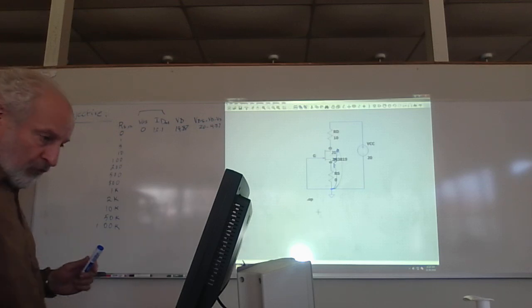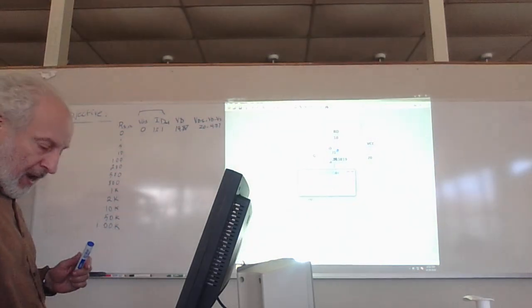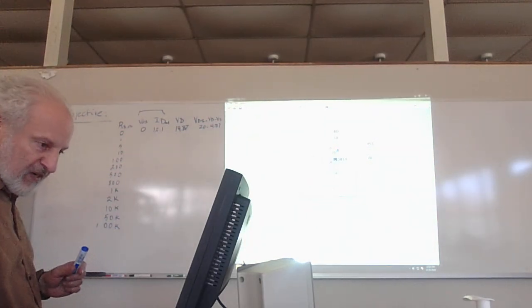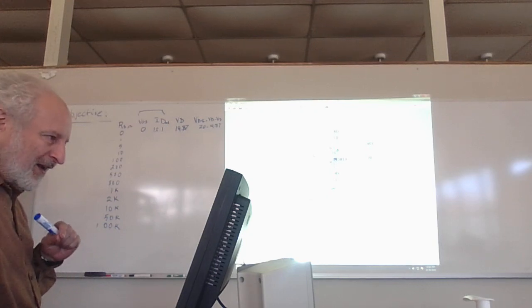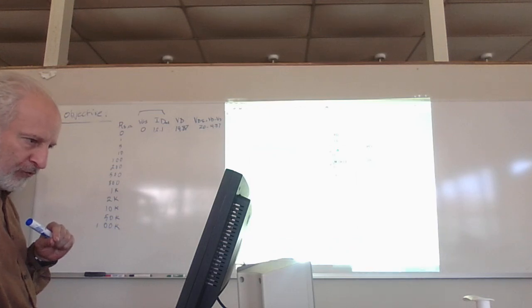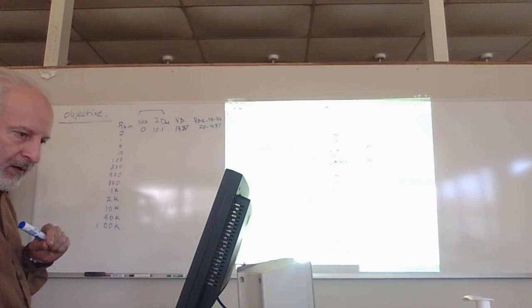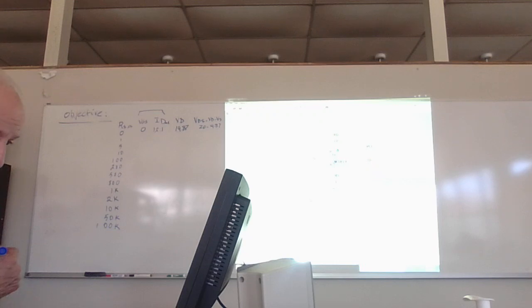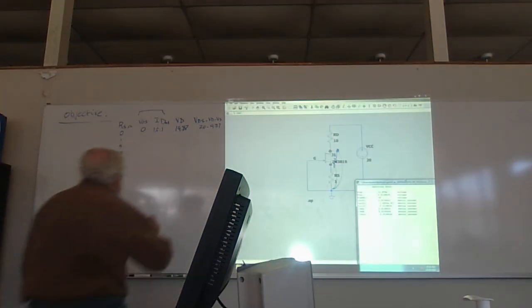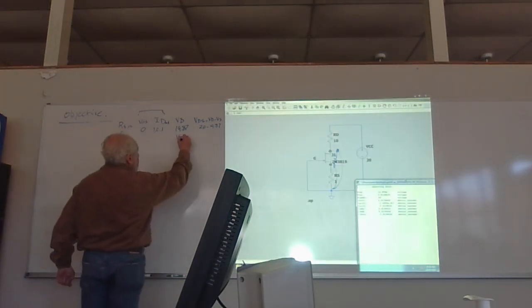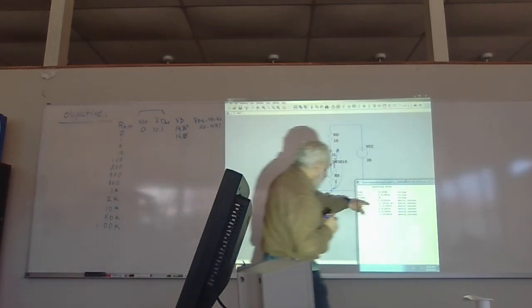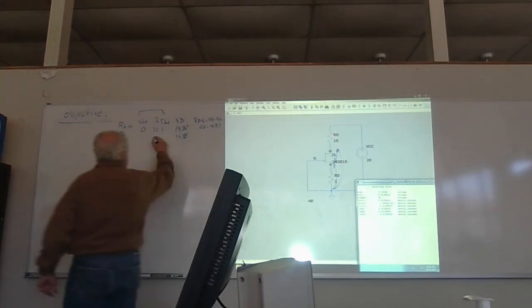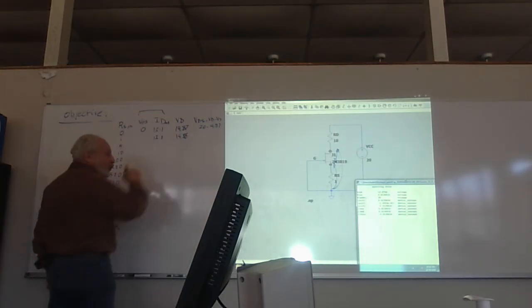Yep. So let's go ahead and run this with 1 ohm. Now, with 1 ohm, we should see a slight difference, but not that much in the current, because we're not resisting the current as much. Okay, good, so the other points showed up. We're still at 19.87, actually almost 88. But this time, notice I'm at 12.0 exactly. So I did lose some current, but not much.